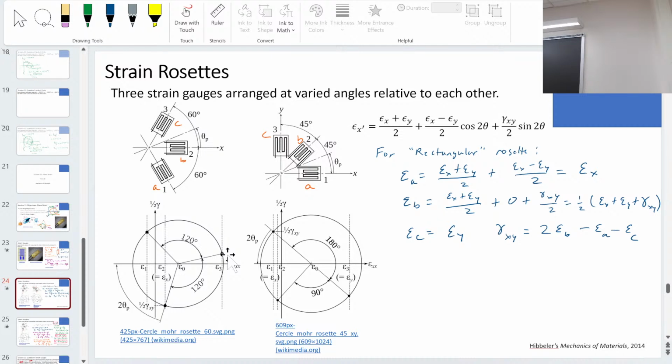It depends on how you define X, because here it's defined as going outwards. This is the beam, this is the wall, so the edge is here. If I cut through here, then the positive shear will be going down, as long as I'm exposing that side, and the normal force will be going outwards. Yes, that's right. That's this case.